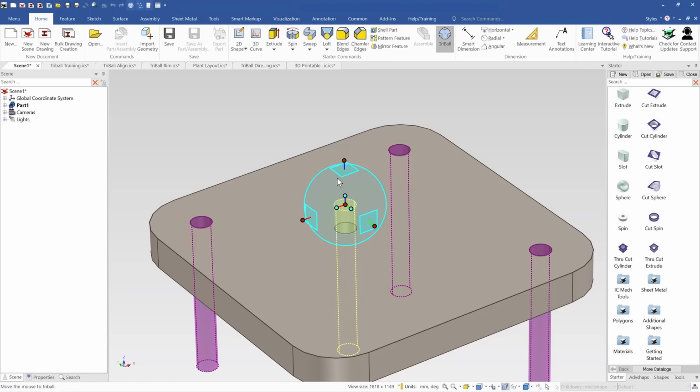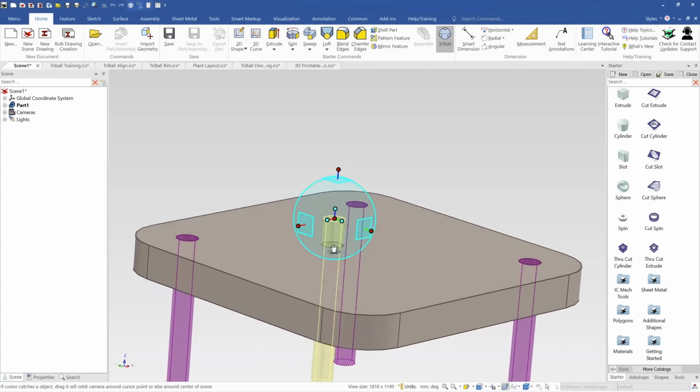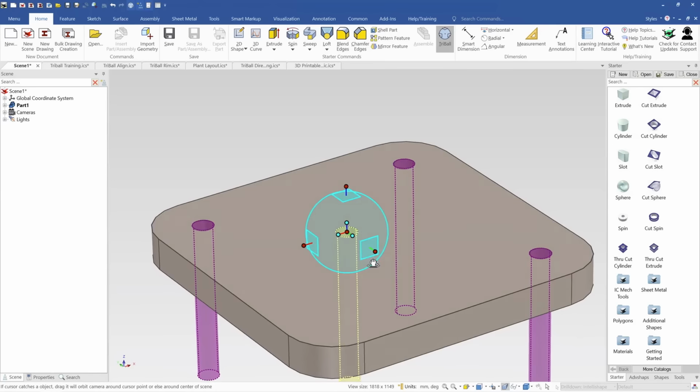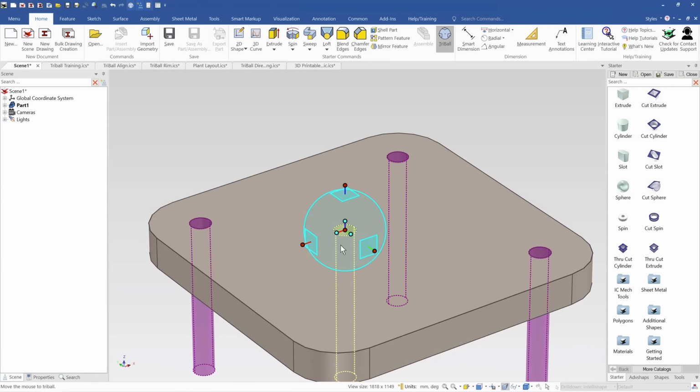That's what the outside handles do. Now the outside planes allow you to position only on a plane. So while these handles later only position on an axis like that, and note you can lock them down at any stage, like I am here. So I've locked that axis down, and I'm going to drag this to this face, dragging the center point, and that's now actually locked my positioning to only go in that axis.